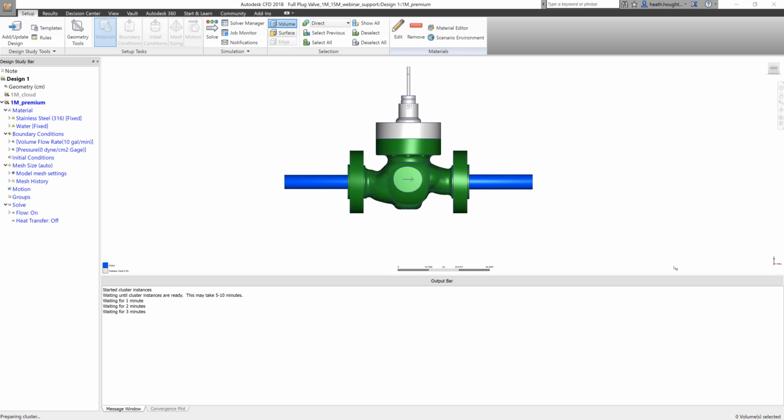That is a completely different scheme for this new solver. And so we've tried to get it to be very comparable. So if you're used to running something for 250 iterations to get a well-converged solution or a fully converged solution, we've tried to make the numbering of the iterations that you see on the client, what you're actually seeing as your inputs, to be very similar. Having said that, still could be off by, let's say if it took 300, it still could take 400 to solve to full convergence with Cloud Premium.